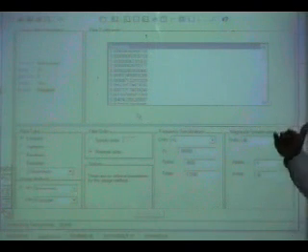So we prefer implementing a filter using the second order. But if you want, for some reasons, B's and A's in a single section, you can go and say, no, I want to convert to a single section. If you say single section, I'll give you first the numerator coefficients, then the denominator coefficients, 31 of these. So this is how you design a filter.